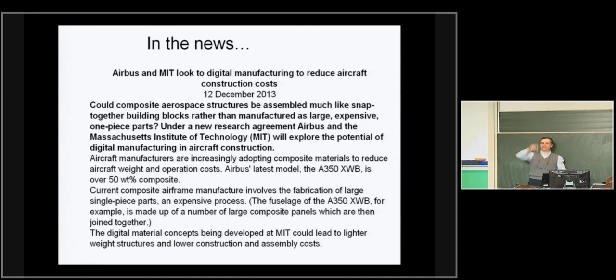And you end up having to put fasteners, the so-called chicken fasteners. That's why it's chicken, because we chicken out. We know that the adhesive is strong, but we cannot prove conclusively that every day we will make the same part with the same process. We will not miss something, and we won't end up with one bond line on one part being a kissing bond. So we use these fasteners, which allow us to go from limit to ultimate load, essentially, and those are the chicken fasteners.